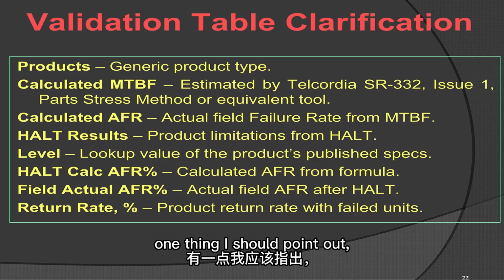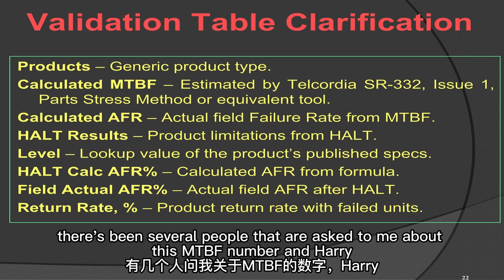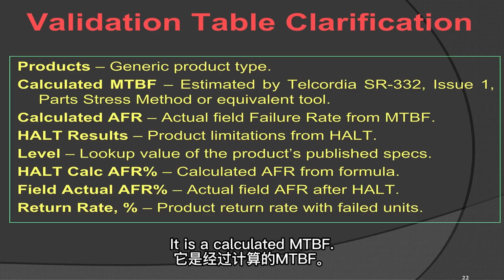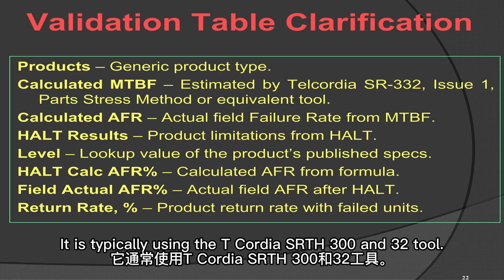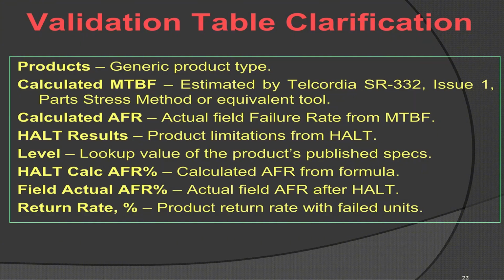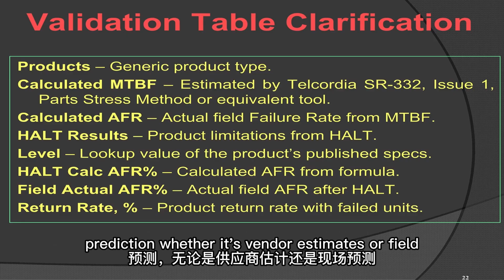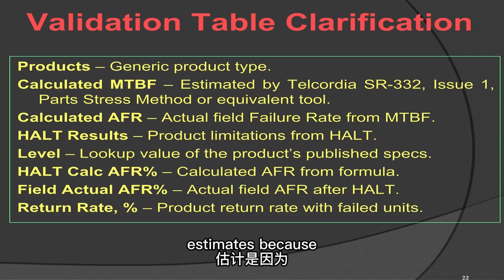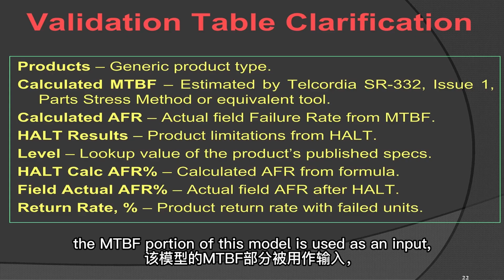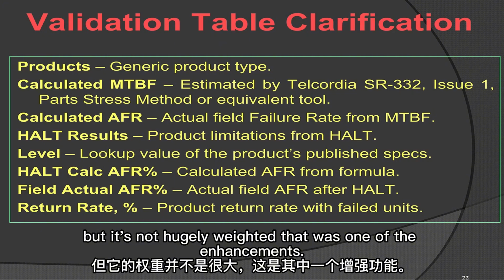One thing I should point out, there've been several people that have asked me about this MTBF number, and Harry puts it right here on the validation. It is a calculated MTBF. It is typically using the Telcordia SR332 tool. It still could work with the mil standard or any other method that you choose to do your MTBF prediction, whether it's vendor estimates or field estimates, because the MTBF portion of this model is used as an input, but it's not hugely weighted.